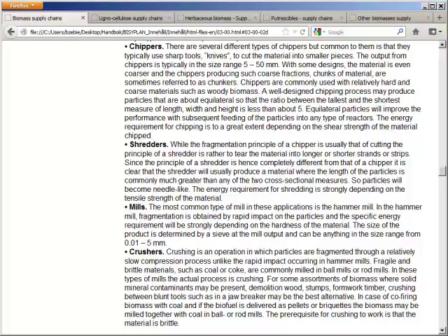For example, in a ball mill or a rod mill, such as are used for coal milling or coke milling. For biomass applications, the material needs to be brittle to be crushed in a crusher. And that means that, for example, wood pellets that are dry and need to be broken up into small particles, or dry demolition wood, can also be disintegrated in a crusher.